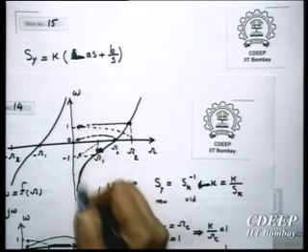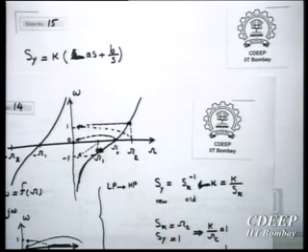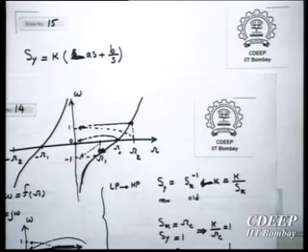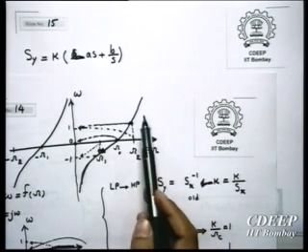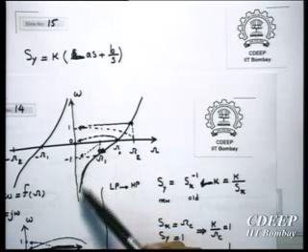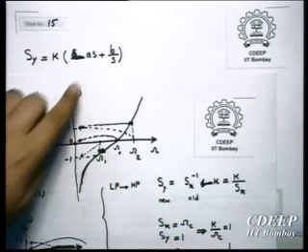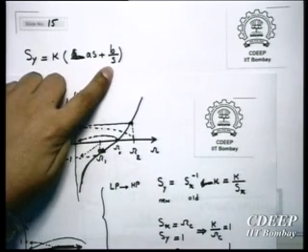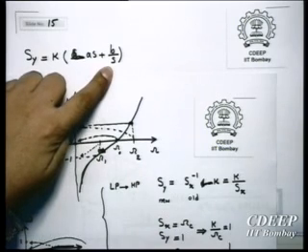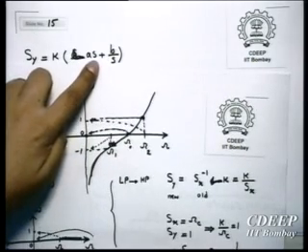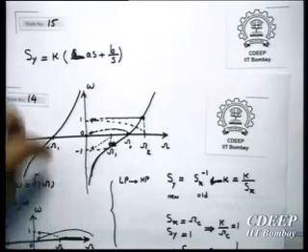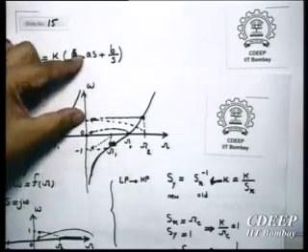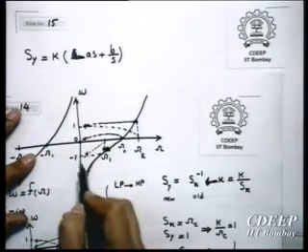It should be. So this is the transformation. Infinite will go to infinite, and 0 also will go to infinite. That is the reason I should have S and 1 upon S, because it's a band pass. Therefore, both 0 and infinite should be transferred to infinite, which is the outer area of this low pass filter.